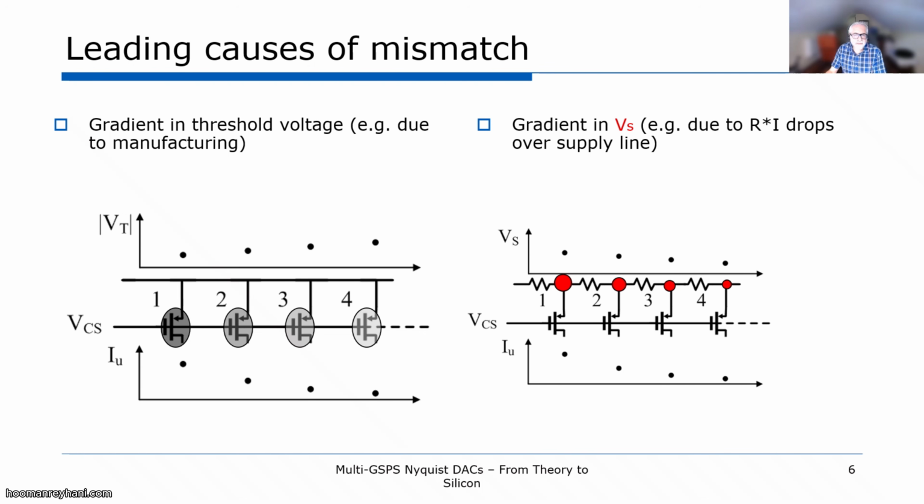On the other hand, if we simply change the order of activation of subsequent devices while the individual mismatch errors don't change, the correlation between the mismatch errors and the output is broken. As a result, the spurious output power spreads over the output noise floor instead of building up on harmonics.